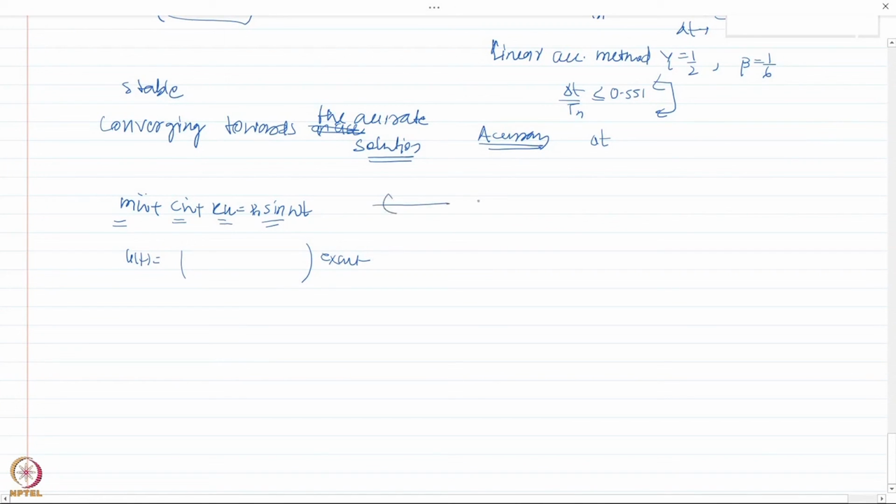But you can employ the excitation interpolation method, or central difference method, or Newmark method, and then compare the response for different values of the time steps and see how accurate they are.